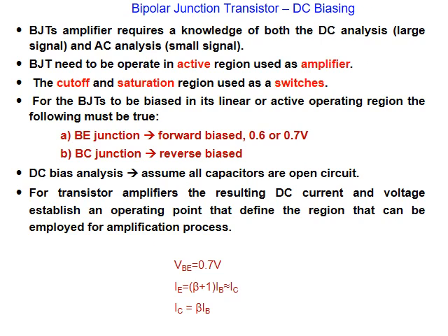Now, first of all, let me remind you of the principles and formulas used before. First of all, usually we expect the transistor to be conducting electrical current, with the base-emitter junction forward biased and the base-collector junction reverse biased. Also, it's worth mentioning that transistors used today are mainly manufactured from silicon, and the voltage drop is around 0.7 volt. And I would also like to remind you that the equation relating emitter current to collector current is (beta plus 1) times I collector, and I collector is beta times IB.